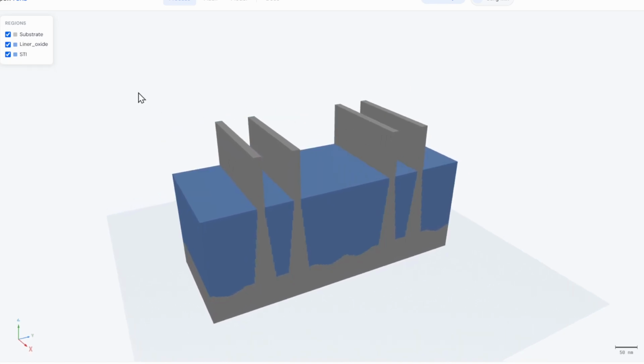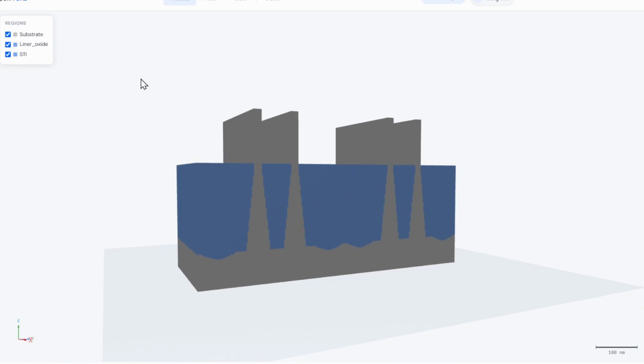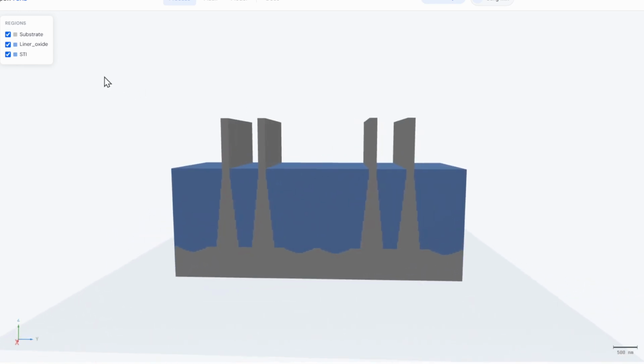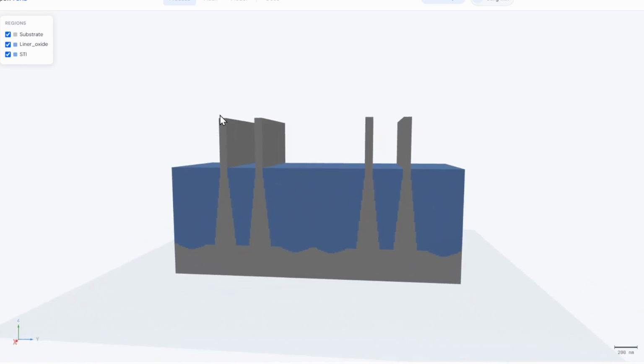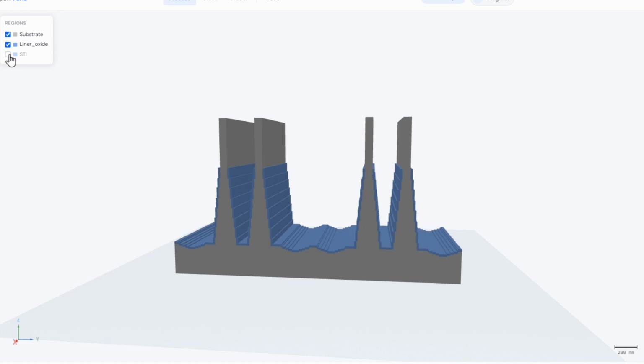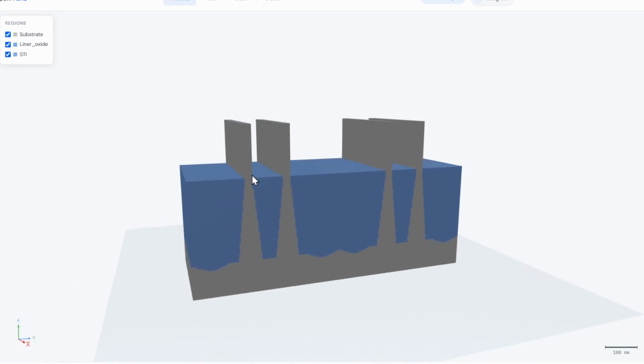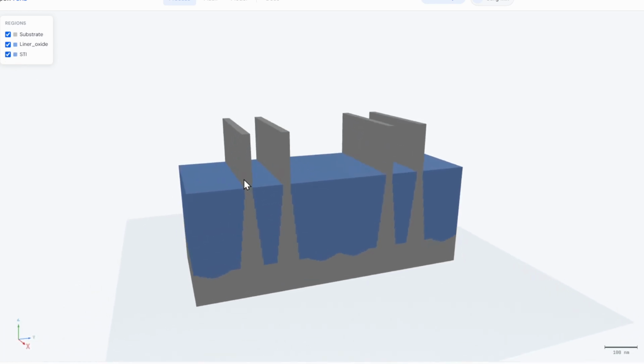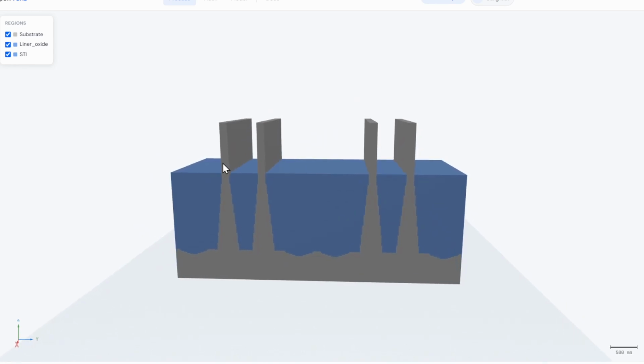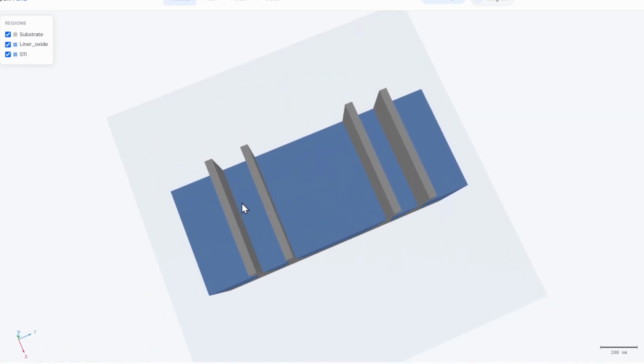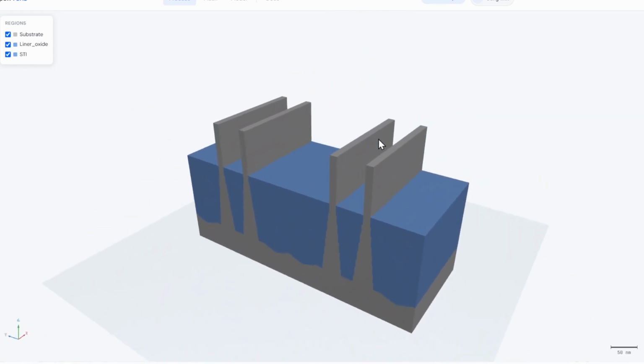By further etching the silicon dioxide, now we can finally reveal this silicon fin. So here we have a sub fin, and that is still isolated by the remaining STI. Yes, and now we have a well revealed silicon thin layer, and its thickness in this case is 7 nanometers.